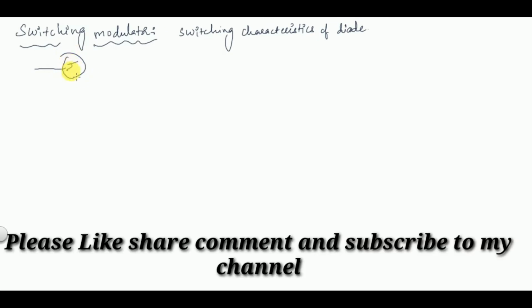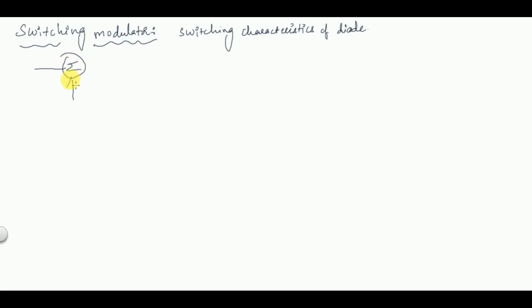It has a summer circuit for which one input is the carrier signal Ac cos 2 pi fct, and the second input is m(t), the message signal. The output is V1, so V1 is equal to m(t) plus Ac cos 2 pi fct, which is the same as the square law modulator case. Here we have a switching device.